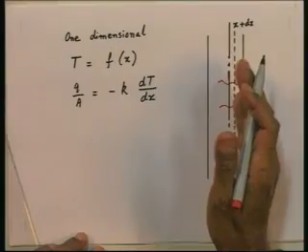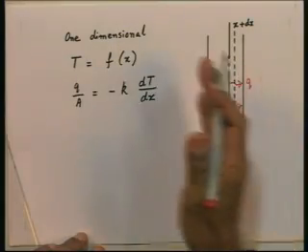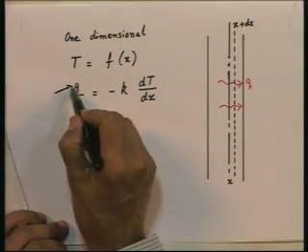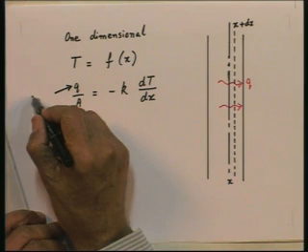But we have already said that the temperature is not changing with respect to time. Therefore, it follows that q across any plane x, x plus dx or x plus 2 dx, whatever, any plane in this slab will have to be the same everywhere. So, q is a constant. That is what we have shown from the first law: q is a constant.